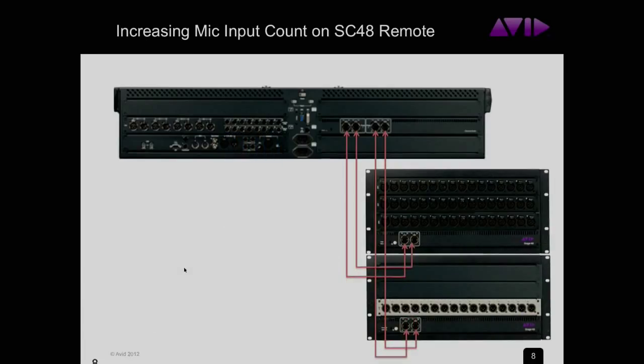All right, let's take a look at another one here where, let's say you had that remote package again where all of your mic line inputs are remote to the stage, your outputs are local to the stage. And you kind of knew from the dictation of the situation that you're in, whatever show you're on, you're thinking, okay, well, I'm still going to need my insert points. I can't really give up those insert points to more pre's out there. How can I manage that situation?